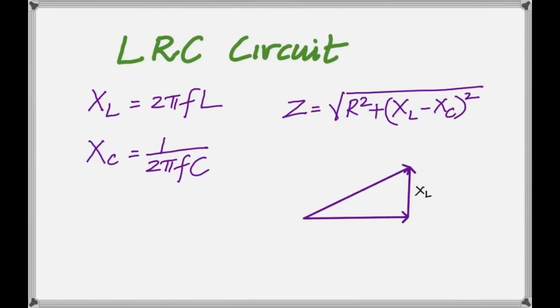That is the phasor diagram that gives you an idea of how they look like, XL. And I just put it, Eli loves ice. And you know what that is? That is just to focus on the inductor. The EMF comes before the current. So the voltage leads the current by 90 degrees. The voltage leads the current by 90 degrees in an inductor.